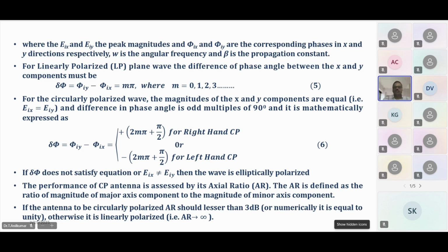You can use dual feeding, and you can use a microwave network to feed the different elements. But according to the shape, if you want circular polarization, you have to bring this asymmetry through slots or other configurations that I am going to show you, right? Next.